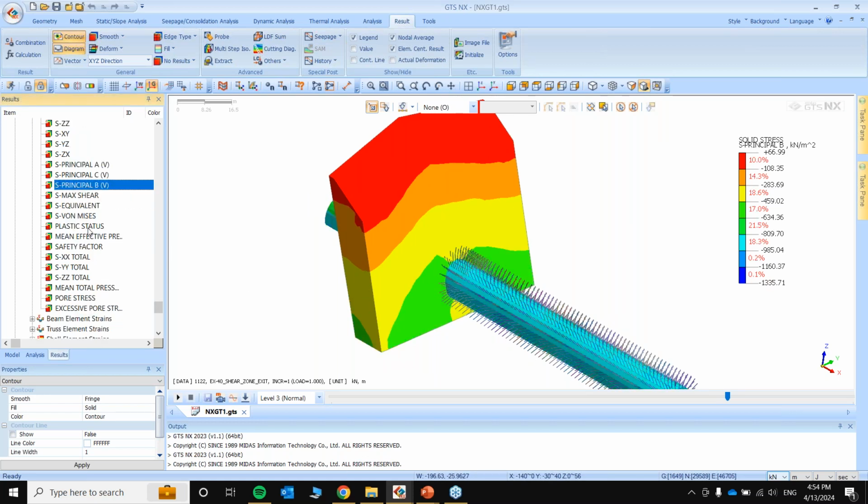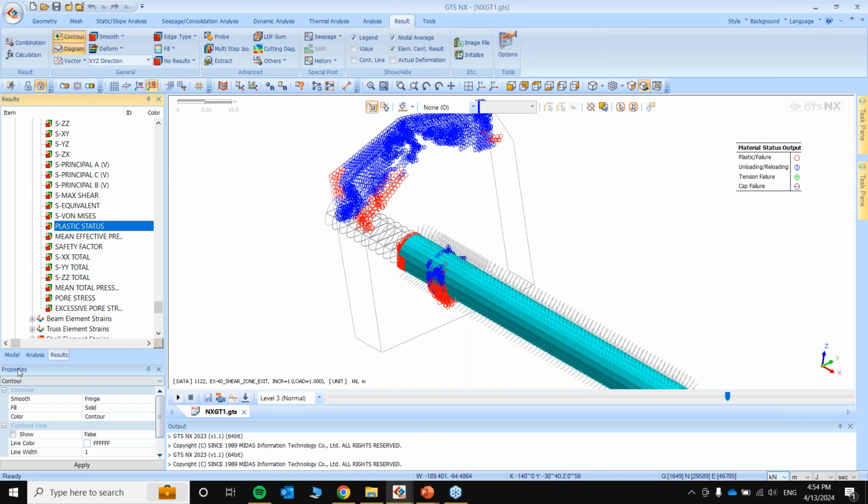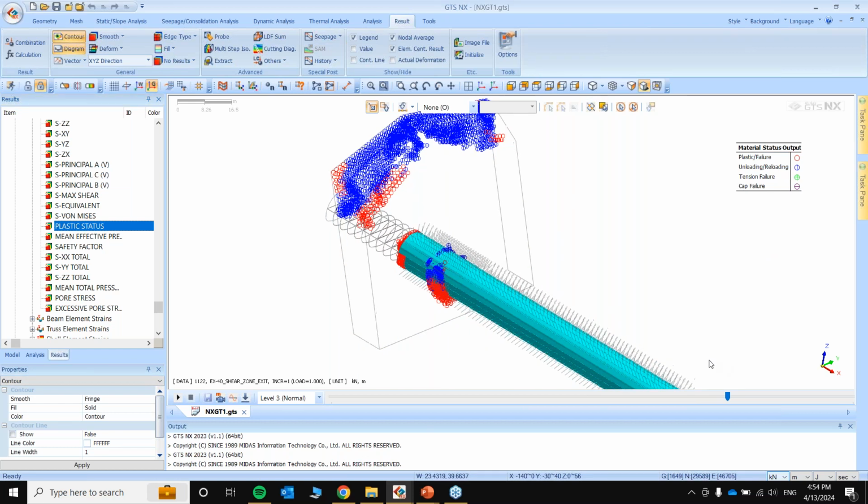Now the plastic radius. So we had three different types of rock, both the outer rocks that were the gneiss and sandstone. They had quite close properties in terms of geomechanical ones. But the culprit here was the shear zone. So the plastic radius that we should assume should be from this part. If you go for plastic status, this is how it looks like.